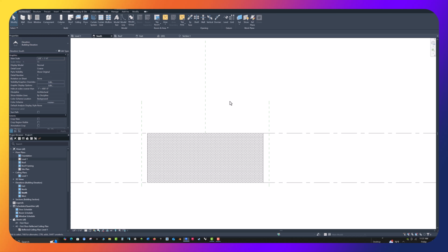I need actually 2 more guidelines. When I create a gambrel roof, I inscribe a square inside a circle to give me my points where the roof changes slope. And once again, it's a good guideline.